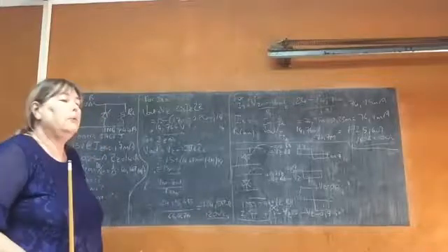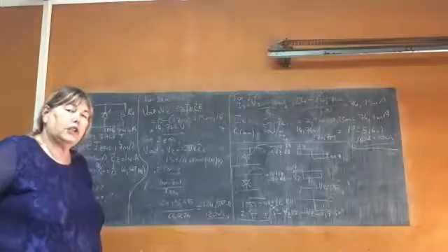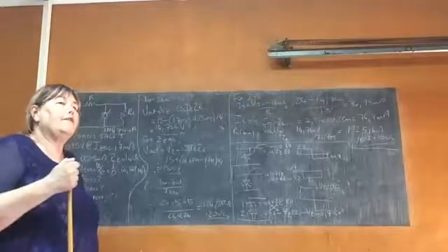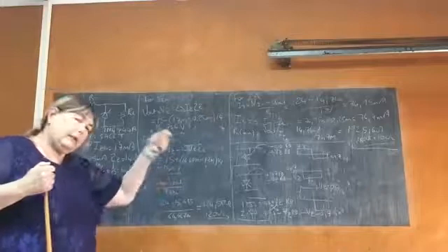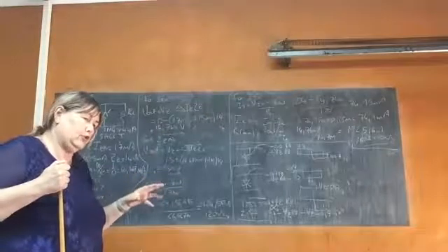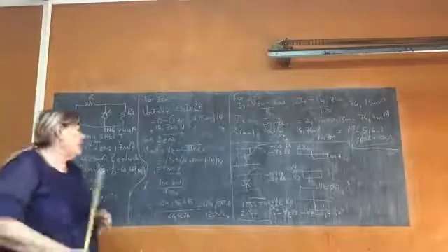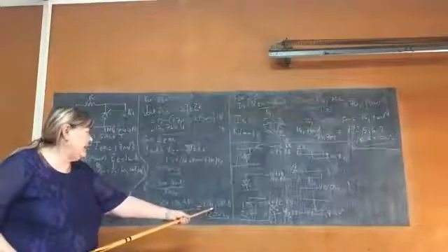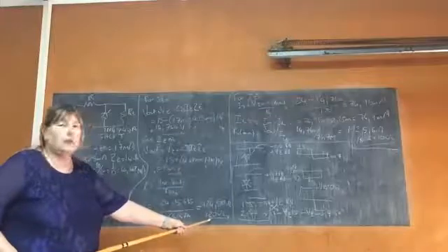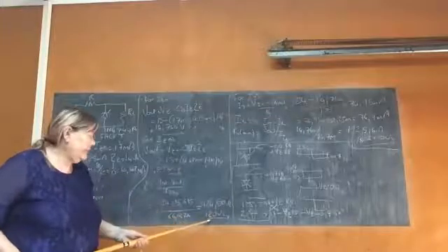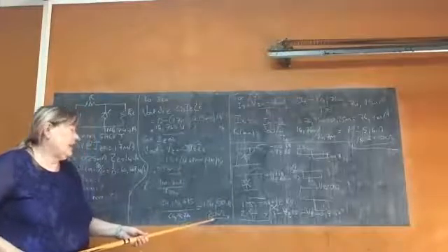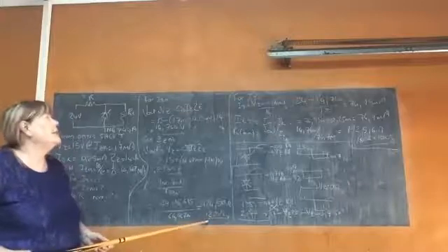Now, we are working with the E12 range. We've done this in the first notes that we did, the first lesson or two. We've done the nearest available value. The nearest available value for 124 ohms is 120 ohms. So now I change it to 120 ohms.